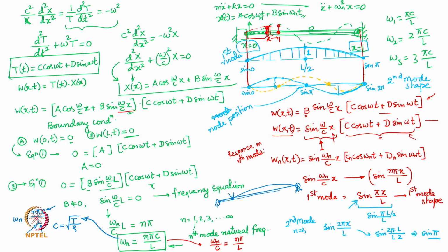So if you want to play the strings generating sounds of different pitch value, you start reducing the effective length of the string, and reducing the length of the string is going to increase the natural frequency of the string. You can try it out yourself: if you pluck the entire string, the frequency of the sound is going to be lower, and if you push this and restrain this part from vibrating, so that the effective length of the string is reduced, you will feel an immediate change in the response. The frequency will increase. This is how these frequencies depend on the parameters of this vibratory system: the tension, the mass per unit length, and the length of the wire.